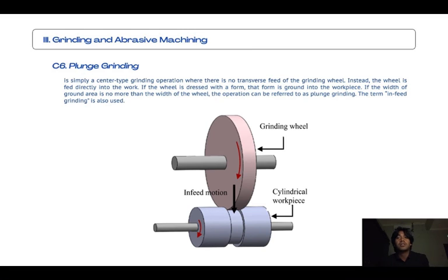The process is less suitable for softer materials that may trap the abrasive. Ceramics, glass, silicon, and mica are machined with this method. Sheets of these materials can be cut and drilled. An abrasive jet can produce intricate holes that would not be easily made by other methods.